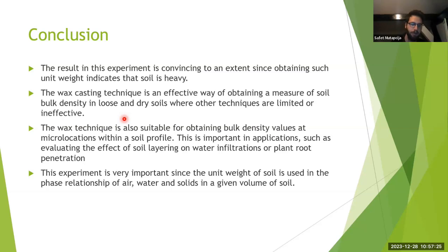After you put your pipeline, you're going to cover it with aggregate or soil, but the modulus of that fill cannot be less than what you had before on the site. So that's basically the reason where your company may have done wrong. Just go back and see whether you met the design requirements for the subgrade of the pipeline, and what the procedure was for filling back the trench. Are there any more questions?